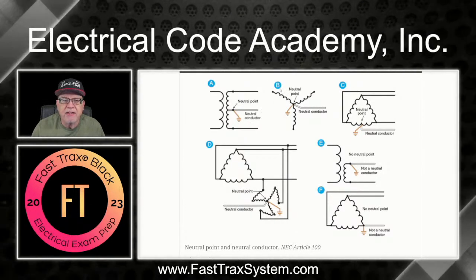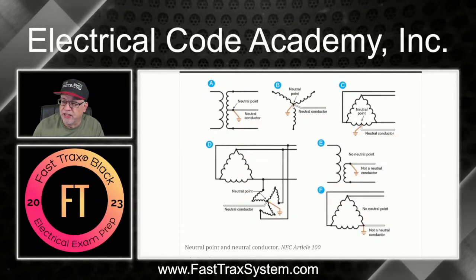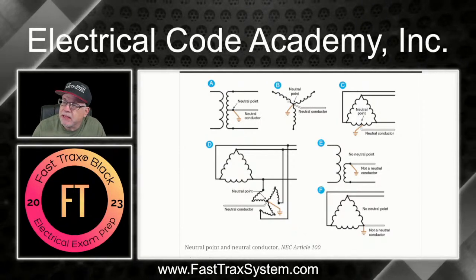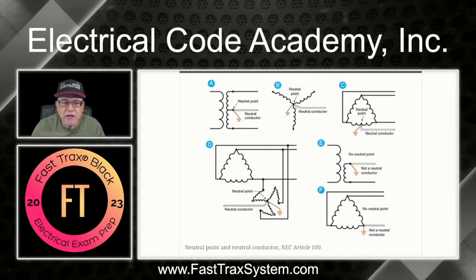All right, this is B. This is the example of a 4-wire, 3-phase Y configuration. Here's the center point, or the common point. In this case, if this was a 208/120 volt system, then from here to here it would be 208, but from here to here would be 120. This is the common zero reference point because this is connected to Earth, and this is where you get voltage stabilization. And this is where the neutral is created.